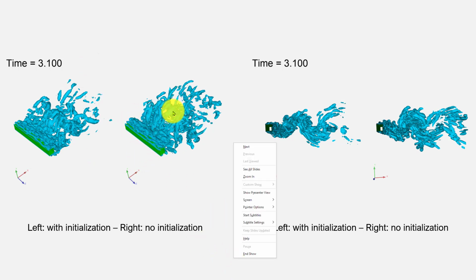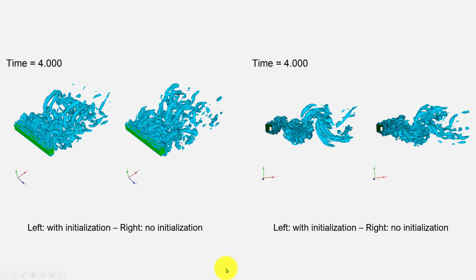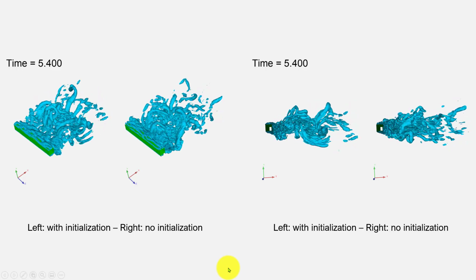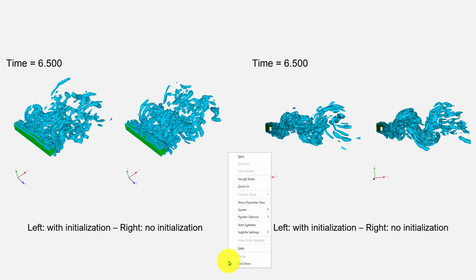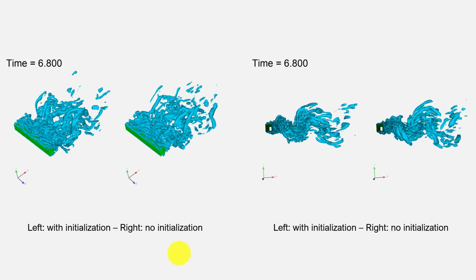It's not 3 seconds. Maybe in 3 seconds you see some vortical structures, but you still need to let it run a little bit so it can stabilize. Probably it's like 5 or 6 seconds until it's stable. In this case it will be fast, but if you have meshes of about 20 million cells, this initial transient of 4 or 5 seconds can translate into maybe a couple of days of simulation. That's why we start from a steady simulation, maybe on a coarse mesh, then interpolate, or even a fine mesh in a RANS run. You can go fast. Okay, so this is the LES simulation, by the way.